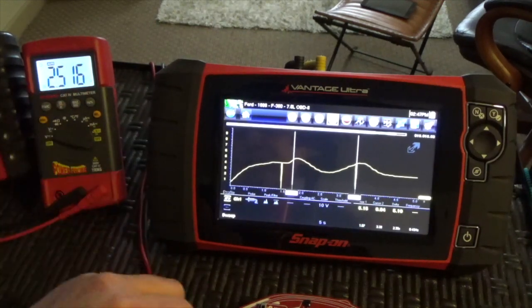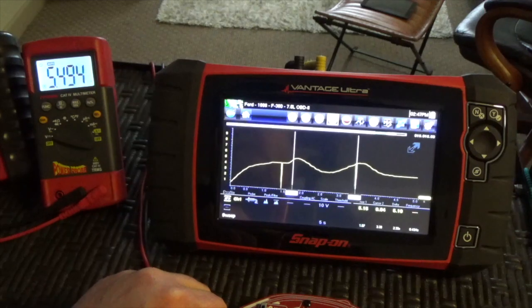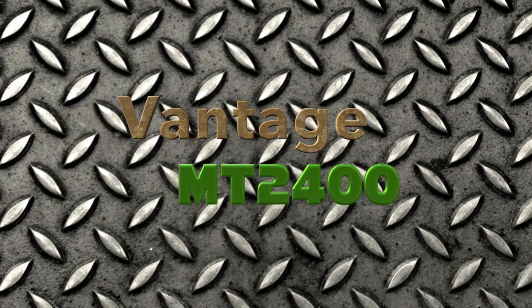Just concentrate on this guy, and you see that will be at idle, that will be fully open or wide open throttle. And you're not going to see more than 5 volts there, unless you have some other problem.